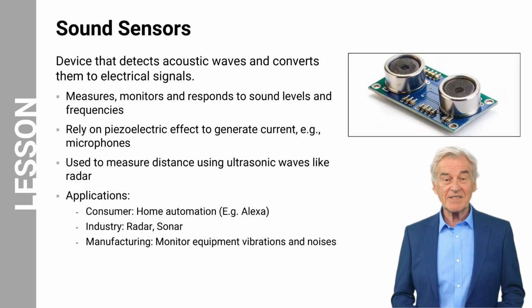Next, we have sound sensors, devices that detect acoustic waves and convert them to electrical signals. These sensors measure, monitor, and respond to various sound levels and frequencies, including those beyond human hearing range. The operation of sound sensors relies on the piezoelectric effect, where specialized materials generate electrical current when they experience mechanical vibration. Microphones are a common example of this principle in action.